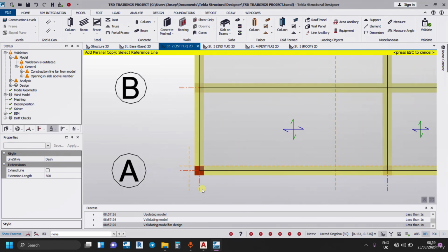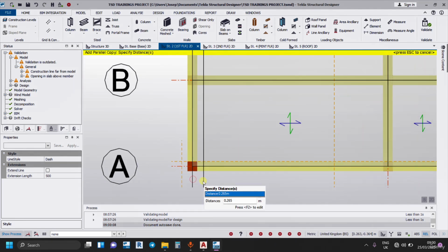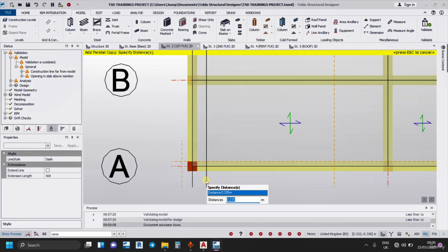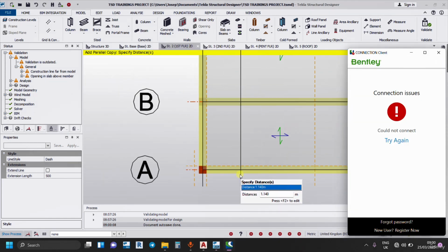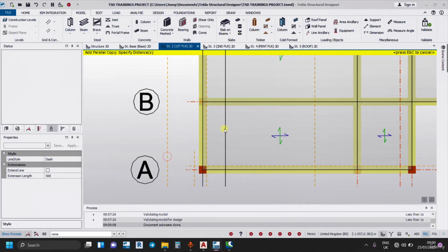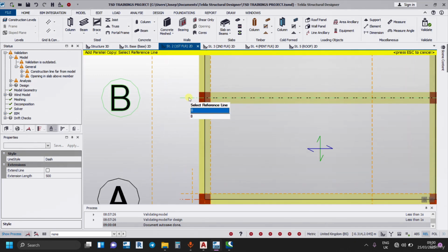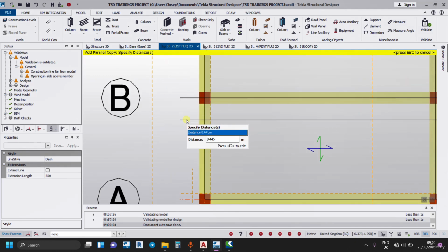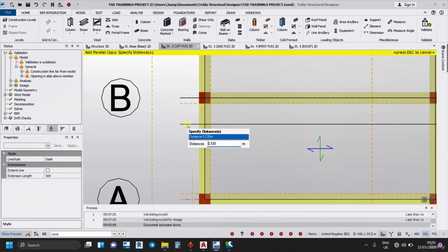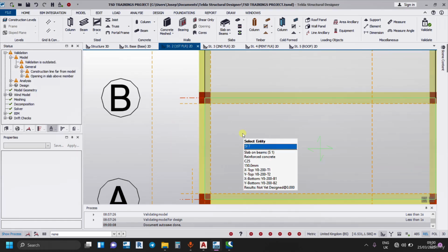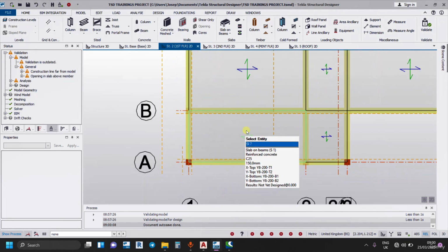I've done that part. Select this, move away, press F2 on my keyboard, 0.115, enter. That one has been created. I'll press escape, select this one, move away, press F2 on my keyboard, 0.115, enter. So with that, the position of the opening has been defined.